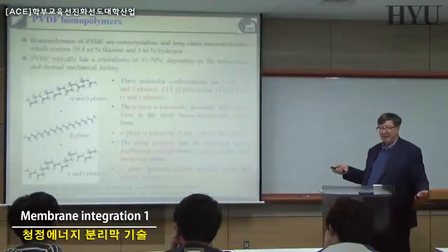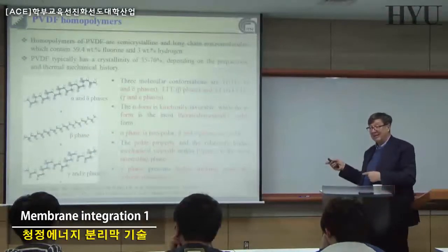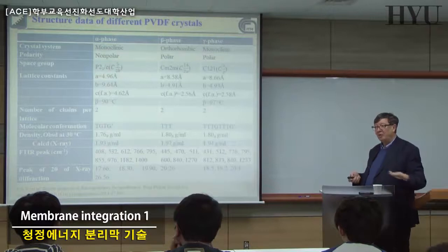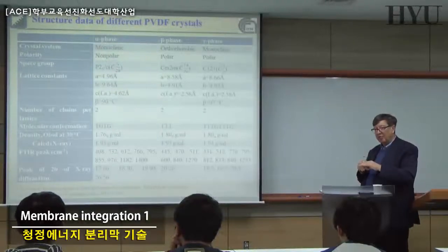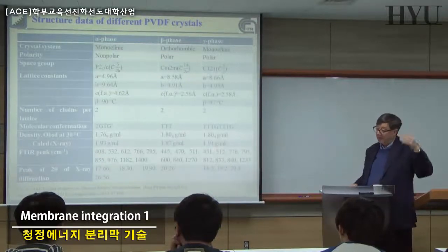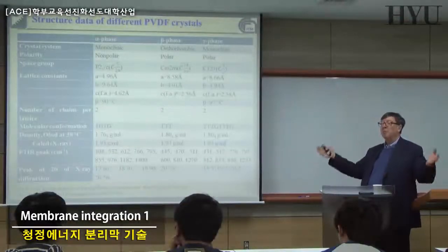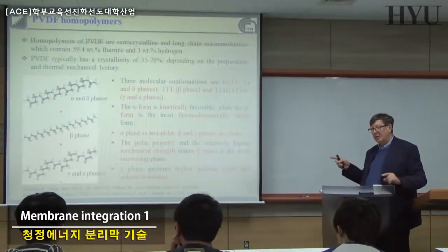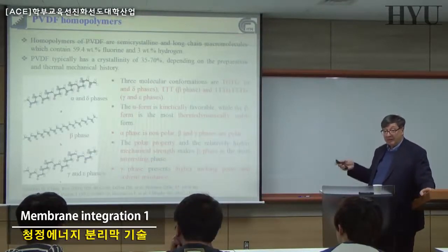And when you form membranes and you want to really keep control of the final influence of this membrane, for example in crystallization, we know that there is a lot of effect on the crystallization related to the surface property. Having a material that is piezoelectric or polar gives you a totally different influence on the crystal formation than a material that is non-polar and non-piezoelectric. So if in perspective we really want to use, as Sierra 2 is predicting, this system to produce crystals, we have to know which kind of PVDF we are using, because that can change the conditions for having the right kind of crystal we want to form, etc.